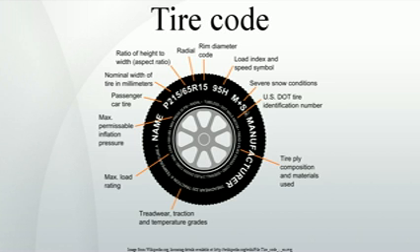Tyre code. Automobile tires are described by an alphanumeric tyre code or tire code, which is generally molded into the sidewall of the tire. This code specifies the dimensions of the tire, and some of its key limitations, such as load-bearing ability, and maximum speed. Sometimes the inner sidewall contains information not included on the outer sidewall, and vice versa.